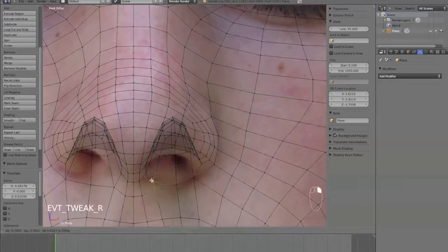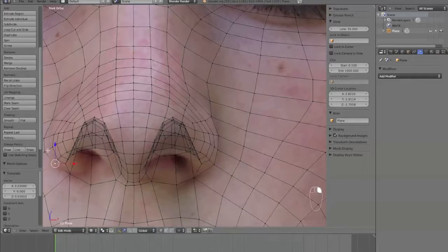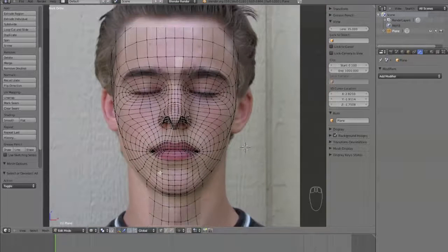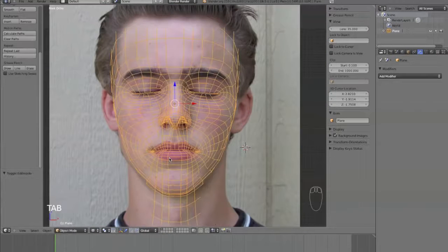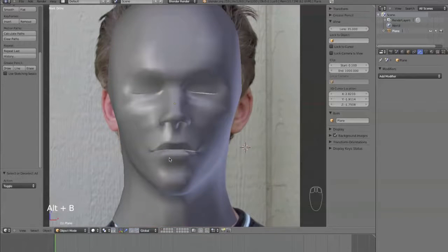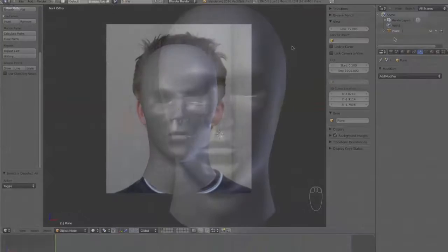It's not that big of a deal while the mesh is still a very low poly, but after applying the subsurf modifier, we got a whole lot more vertices, so it would be pretty hard tweaking the front of the mesh with all those verts on the back getting in the way of us working. To clear the restricted view, press Option B on your keyboard.